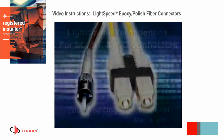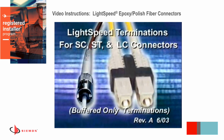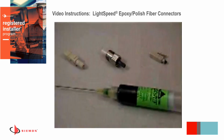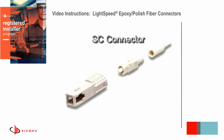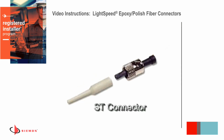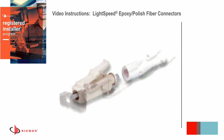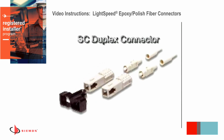The Seaman Company fiber termination process uses a highly reliable acrylic adhesive and polish method featuring our Lightspeed brand activated cured adhesive, and has proven to produce superb repeatable results for long-term reliable performance. Seaman offers 3 standard connector styles for use with this method. The buffered termination process is identical for SC, ST, and LC style connectors. For clarity, the SC connector is the primary connector shown throughout this video using a 900 micron buffered fiber.